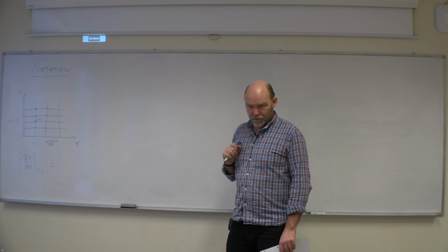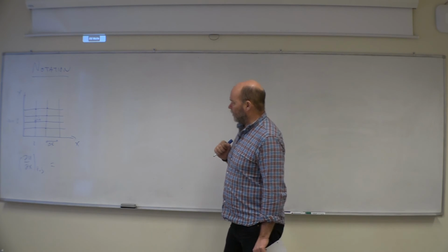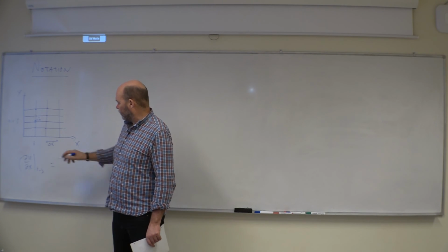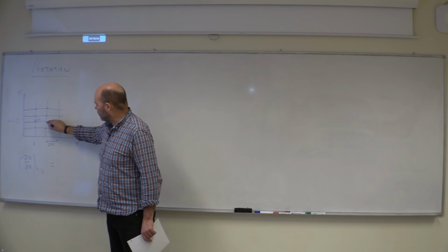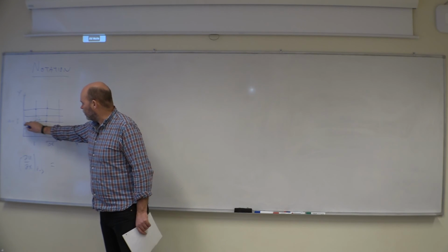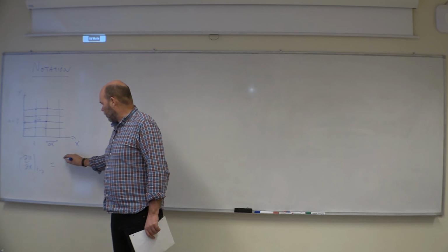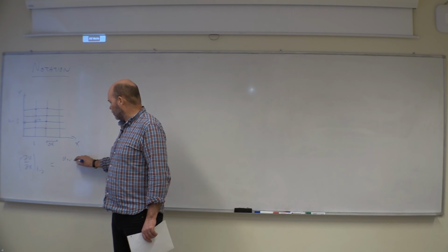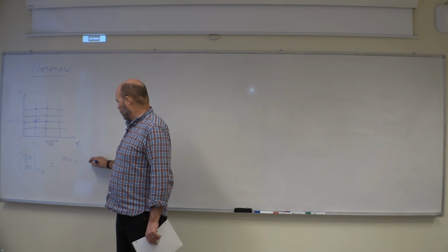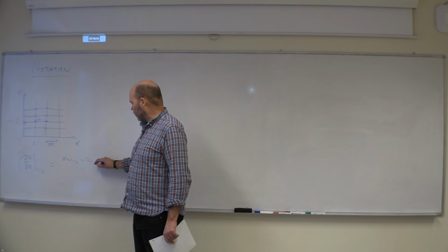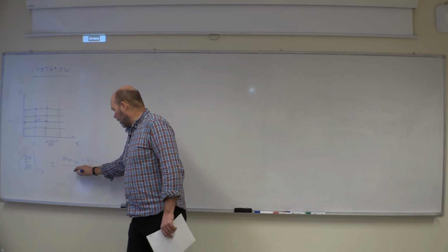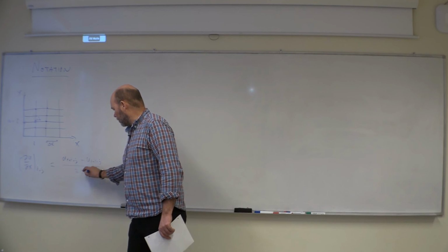Well, if I want this central space scheme, second order accurate, then you need the two neighboring points on each side. So you're going to need u at point i+1, j, minus u on the other side, i-1, j, divided by 2 times delta x.